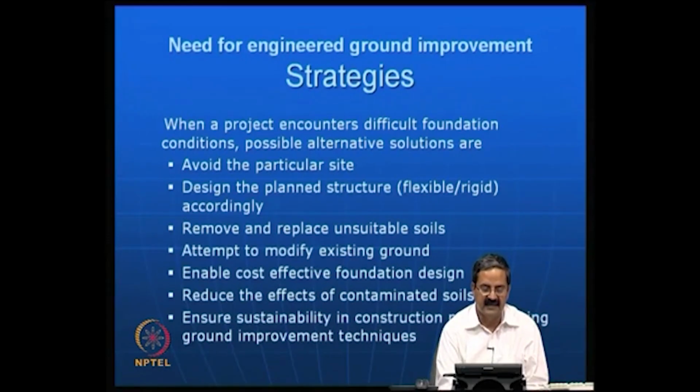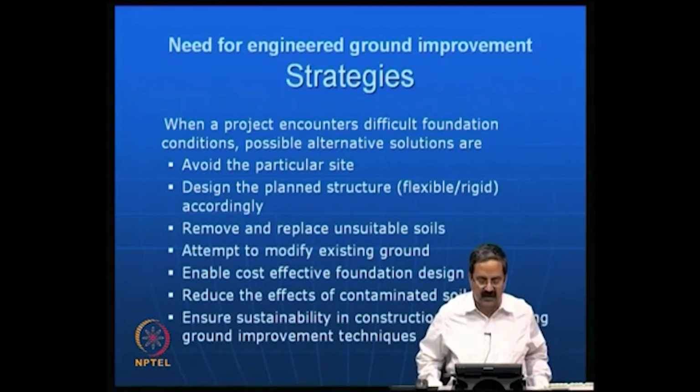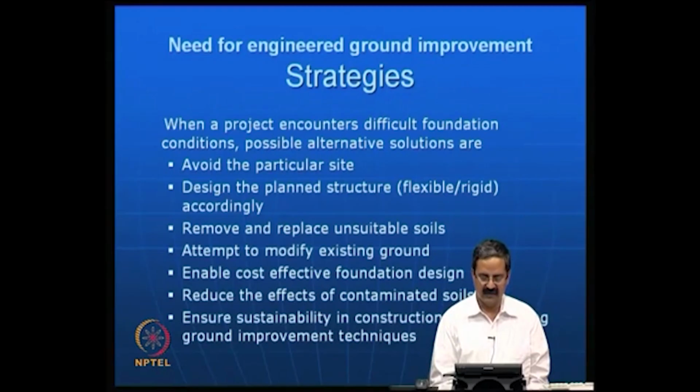The beauty of these techniques is that the foundation cost is cheaper. As I just mentioned, instead of providing thicker reinforced concrete foundations, you are providing thinner sections. In fact, sometimes you are eliminating concreting totally, which is very unique, particularly in a foundation system. If you are reducing the number of piles or removing the possibility of piles itself, it is a very good beginning, because nowadays we are talking about saving materials like steel and concrete, as they are going to be very expensive. So, one can come up with cost effective technologies or methods for foundation design itself.